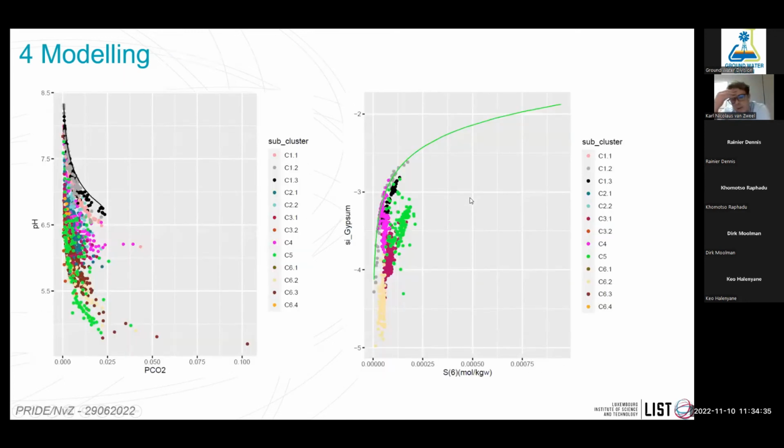So this more or less explained the deeper flow lines actually quite well, just DOC, because we see a lot of DOC leaking into the deeper stuff through preferential flow paths. So theoretically, if you have a homogeneous porous media, your DOC will be oxidized way before the time the water arrives or recharges at the deeper part. So you have to have preferential flow paths for that to get the DOC down there. And this more or less explained what we saw.